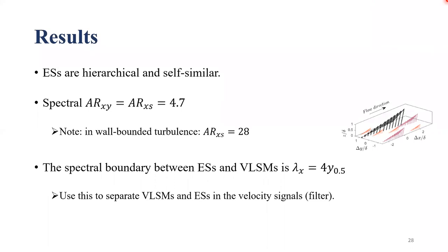But shouldn't it be the other way around? At the center line the eddy should be large, and away from the center line the eddy should be smaller, because eddies are no longer created once you exit the pipe. So when I say far away from the center line, I'm not very close to the edge of the turbulent non-turbulent region. I'm still pretty much inside the shear layer, if that makes sense. Yeah, sort of. I have to think about it.